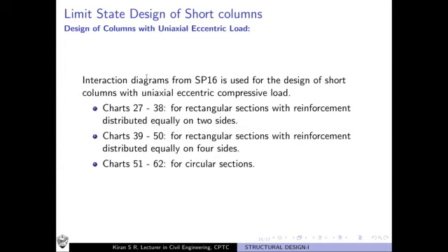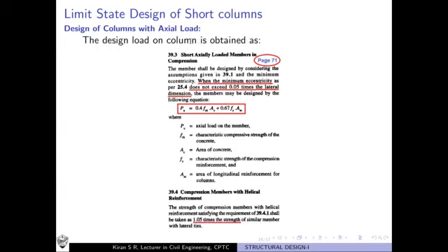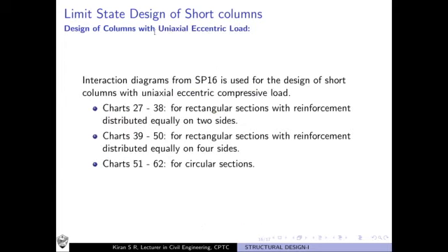Now, coming to the design of columns with uniaxial eccentric loads. So the previous case was for columns subjected to pure axial loads. Here it is for uniaxial eccentric load, the compressive load with eccentricity about one axis. In this case, the design becomes slightly complicated, but to avoid such complications, we make use of SP16 charts. We call them interaction diagrams.